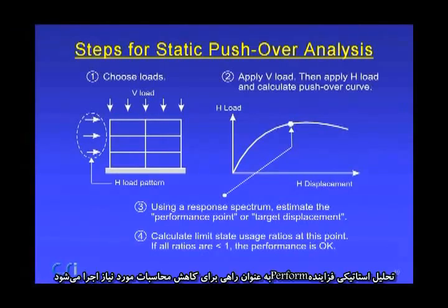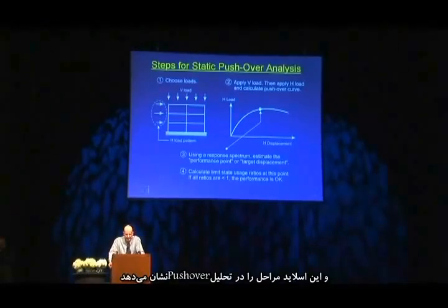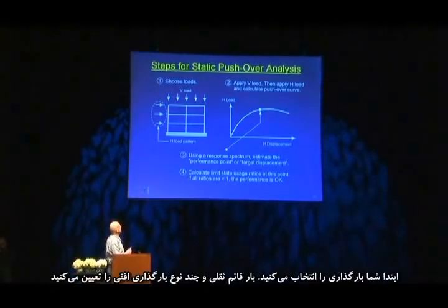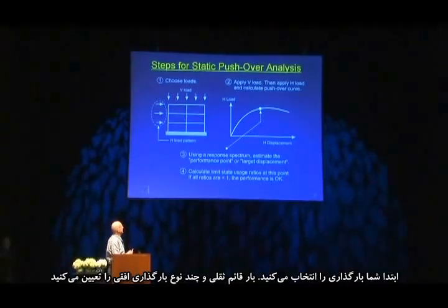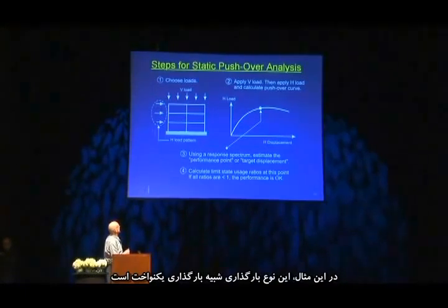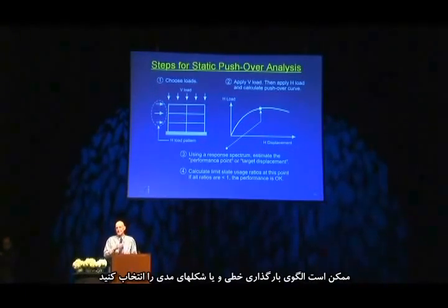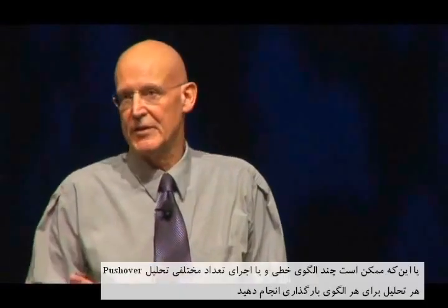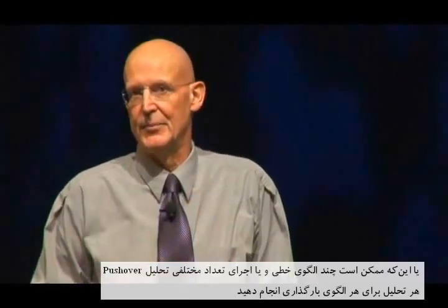possibly time-consuming analysis. Static pushover analysis has been around as a way to reduce the amount of computation, basically. And this slide indicates the steps in pushover analysis. Firstly, you choose the load, you specify the gravity load vertically, and some horizontal load pattern. In this case, it looks like almost a uniform load pattern. You might be linear, or you might base the load pattern on the mode shape, or you typically would have several load patterns and run a number of different pushover analyses, one for each load pattern.